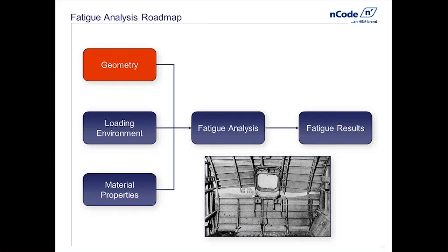That meant then that there was a pressure cycle of 0 pressure differential through the skin when it was on the ground, to the interior being overpressurized relative to the 30,000 foot atmosphere when it was up high. So that cyclic load, pressure, depressure, pressure cycle, or what some in the aerospace industry call the ground-air-ground GAG cycle, along with a high stress concentration, led to an absolute disaster. And this is the reason why we talk today about Airbus rather than de Havilland.